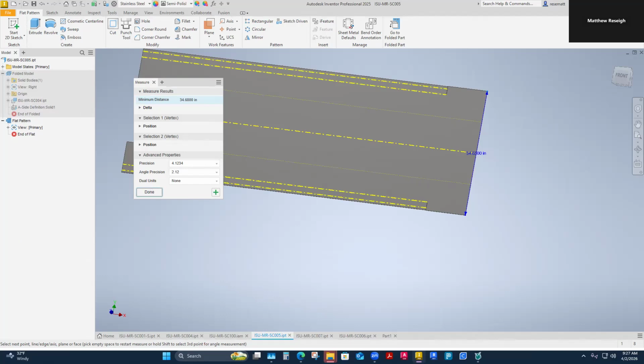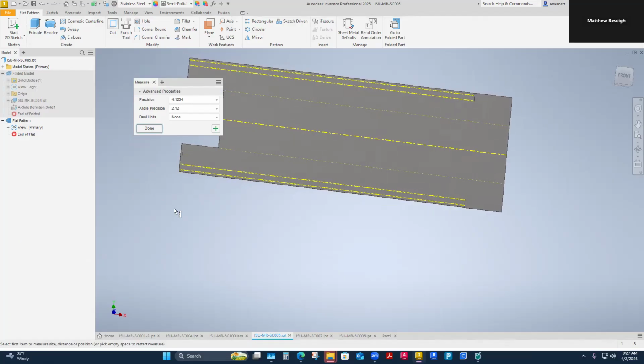And there are times when there are specially sourced things that I need to get. I need to recognize that early on in the design process and get purchasing the lead time. The most lead time they can get to order materials, the better. Then I design under those constraints and pay attention to it as I go, rather than figure it out after you've already spent months designing, you send it to production to produce, and now they've got to spend 6 weeks waiting for the material to show up.